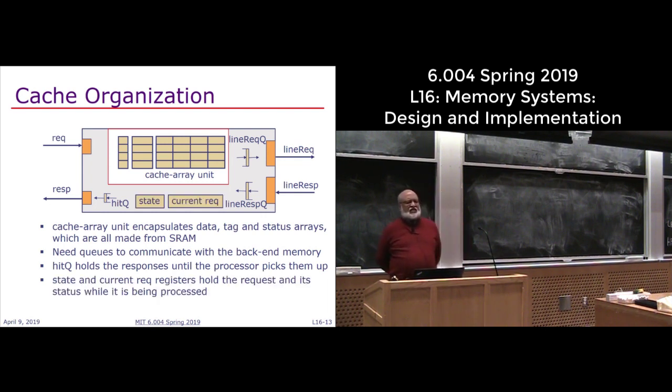Now, as you can guess, inside it, it may take a while to process a request. The best case is you come, you hit it, you put it in the hit queue. But suppose you get a miss. Well, now I have to remember something about this request, because I'm going to send the request somewhere else. I'm going to send the request to the DRAM. And not only that, that's not enough. I may have to write something from here to there. It's going to take several steps.